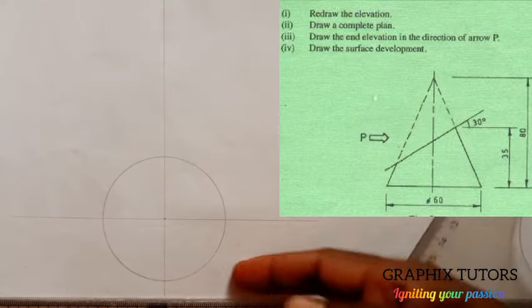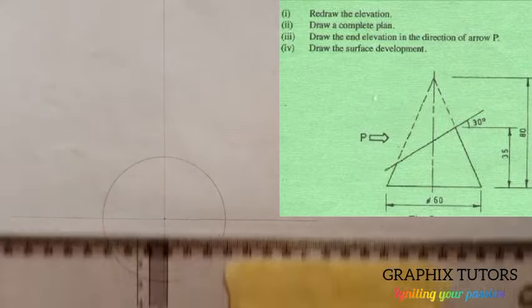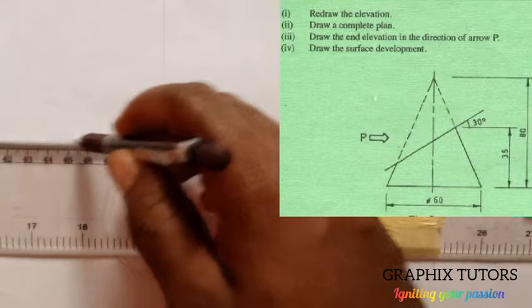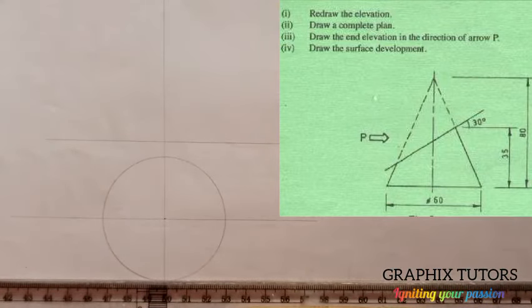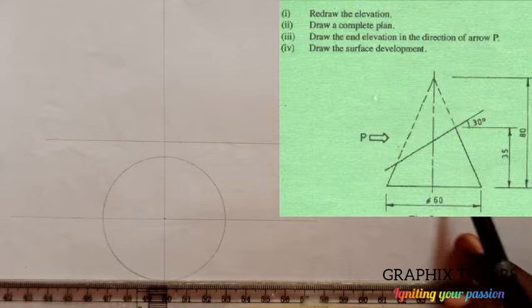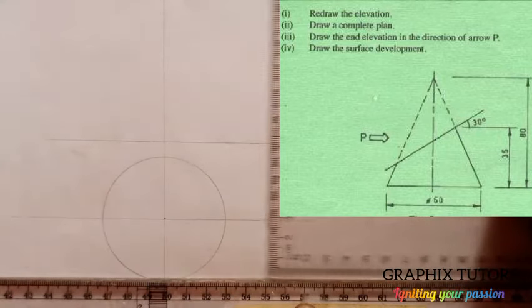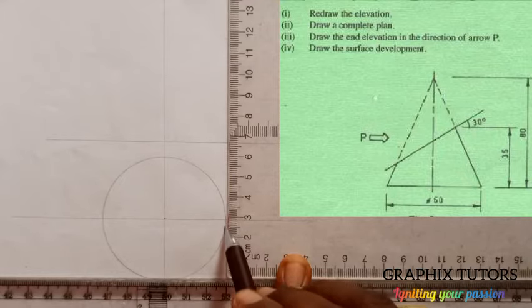Now you need to project the axis upward. Before you project the axis, you should draw a line this way, a front line also, right? That will be representing the base of the front elevation as shown in the figure here. Now, if I project two axes of the two ends of the circle, right?